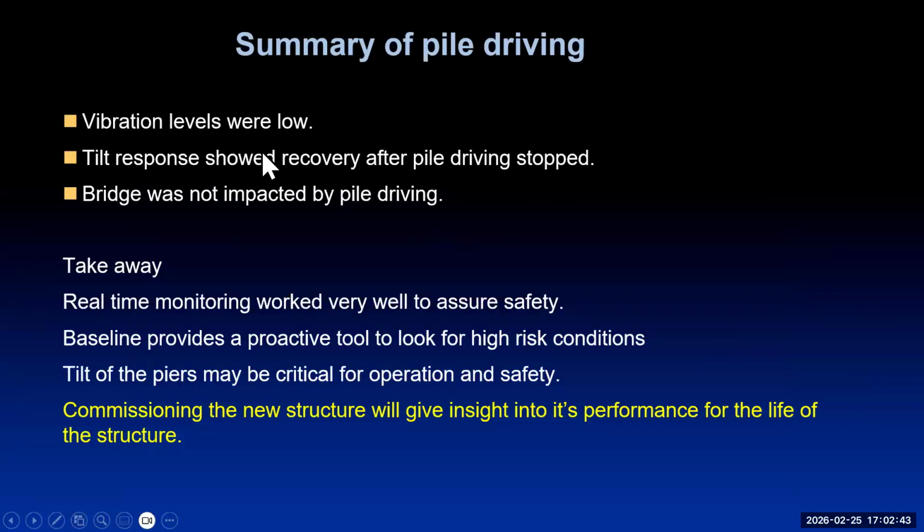So in this particular case, the vibration levels were low. The tilt response showed recovery. The bridge wasn't impacted by pile driving. We were able to go back and say that. So we had the dynamic characteristics. We knew how it was moving left and right and vertically. We could see each one of these impacts, and we could see how the structure responded and recovered. So it was quite an interesting takeaway.